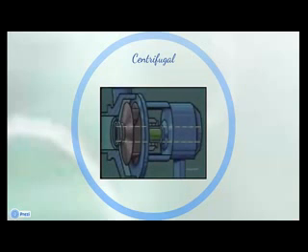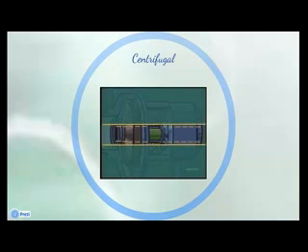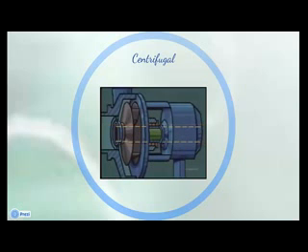The internal parts of a centrifugal pump are mounted on the pump shaft. It's a single piece of metal that's been machined to fit the pump perfectly. The shaft is usually made of stainless steel or some other corrosion-resistant material. And for a very practical reason: replacing broken or worn-out shafts is expensive. Some pumps have a shaft sleeve, or metal cylinder that fits over the shaft and protects it from damage. It's easier and cheaper to replace this sleeve than the shaft itself.